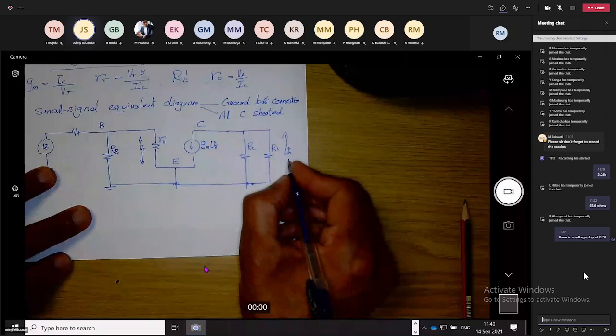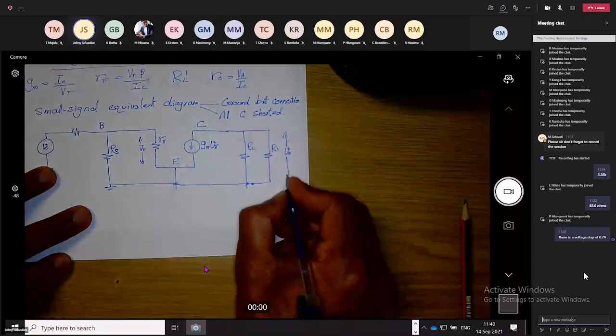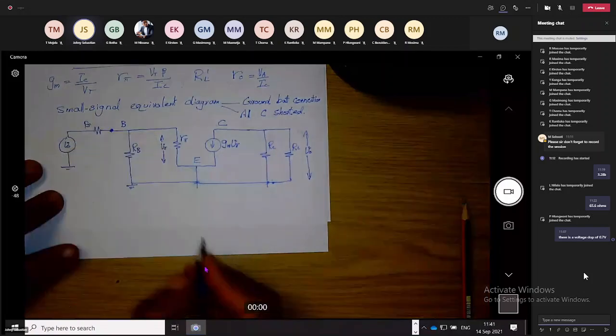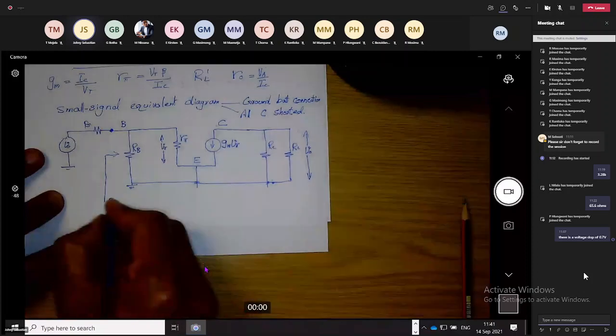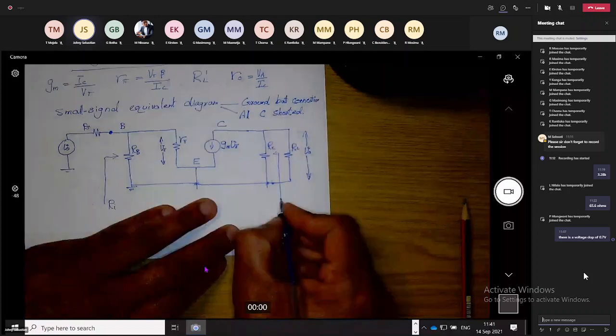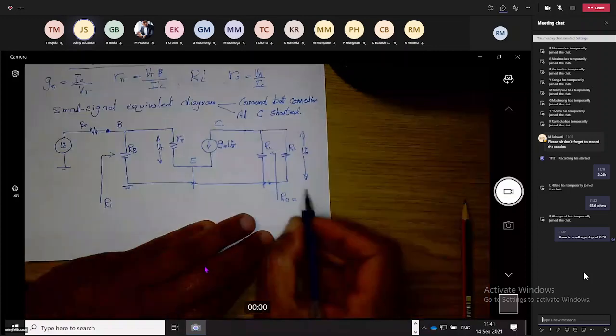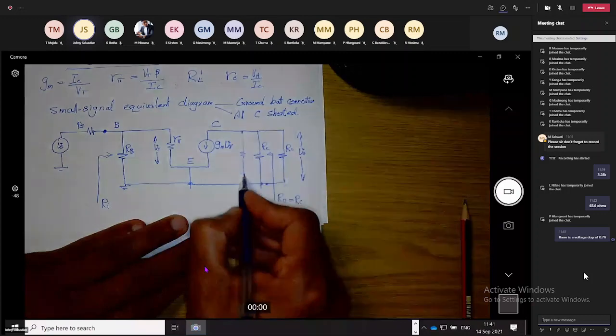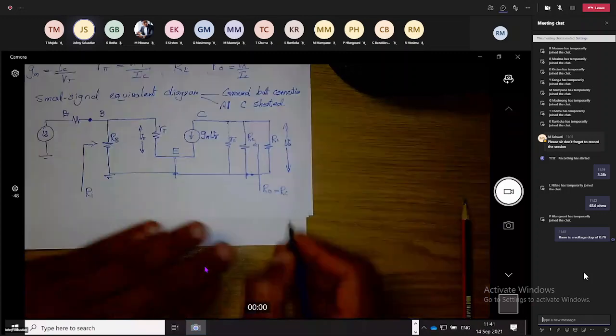Now, looking at the input, that is the amplifier beginning point. So, that is your input impedance. Looking at the output, there is your output resistance. Output resistance is RC. And if you are including R naught, then we simply say R naught parallel RC.